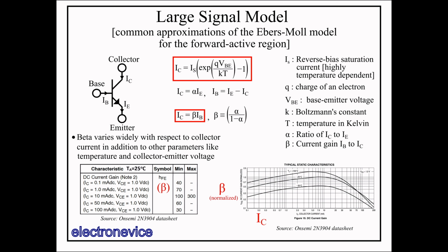So how do we determine collector voltage? Well, effectively by omission, the large signal model indicates that the collector voltage does not affect IC, IE, or IB, and so the collector voltage is determined by whatever voltages and impedances are connected to the collector. This makes the system look like a voltage-controlled current source, where the collector current is controlled by VBE and is unaffected by changes to the collector voltage.